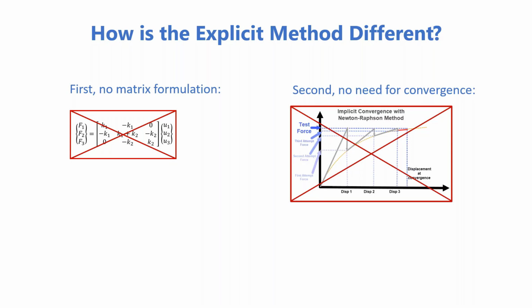If anyone here has tried running a nonlinear analysis where the conditions of the system change really rapidly, let's say your material goes from an elastic state to a plastic state, you'll notice that the time steps start converging more and more slowly as time goes on, as that system becomes less and less linear.